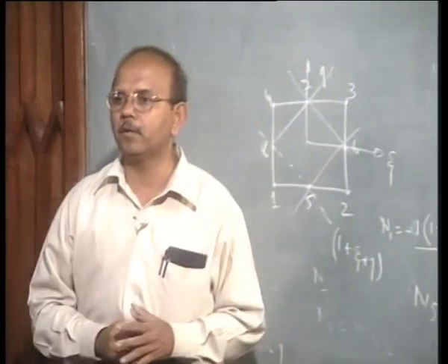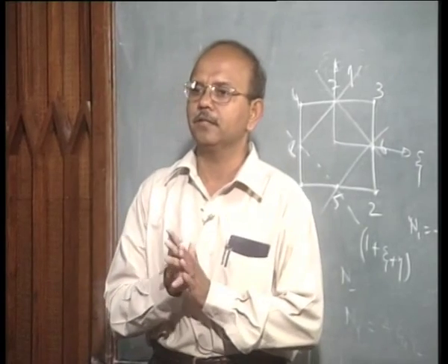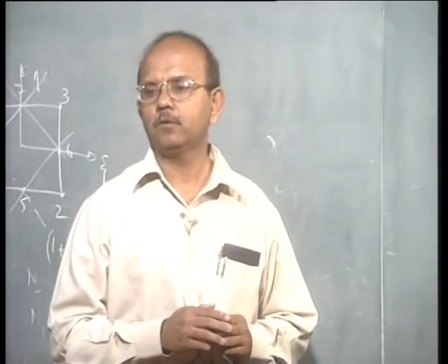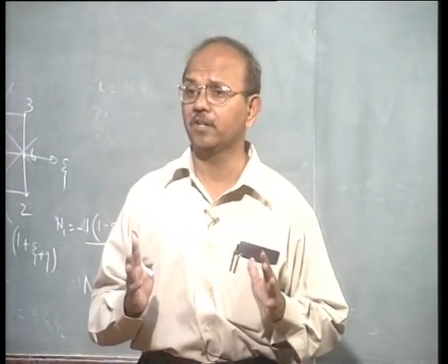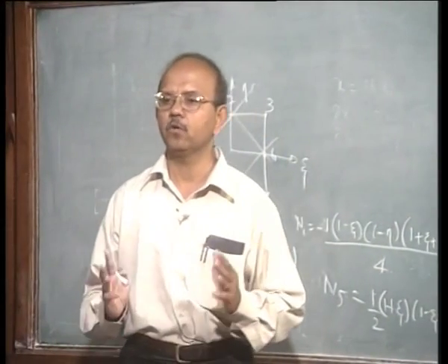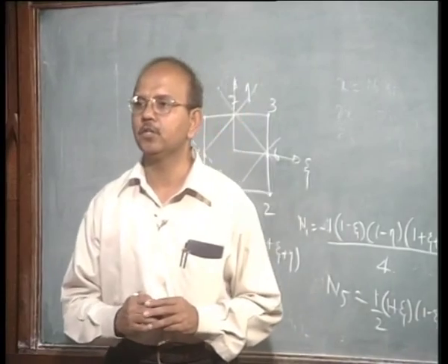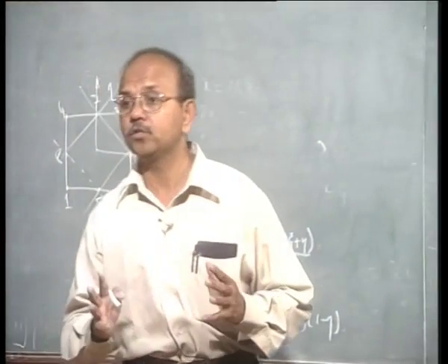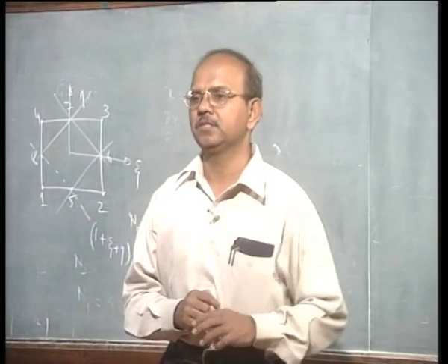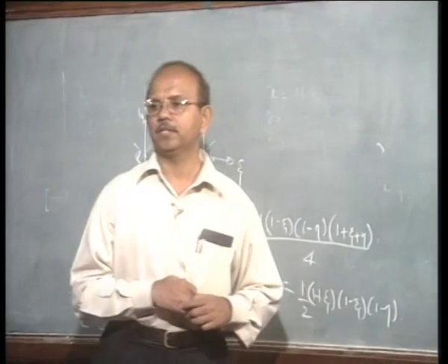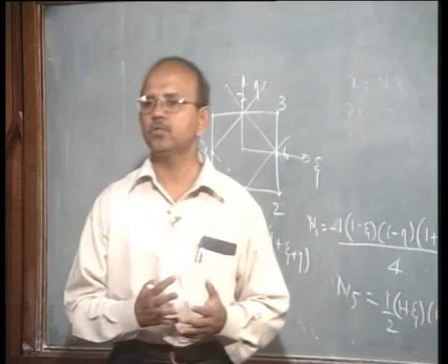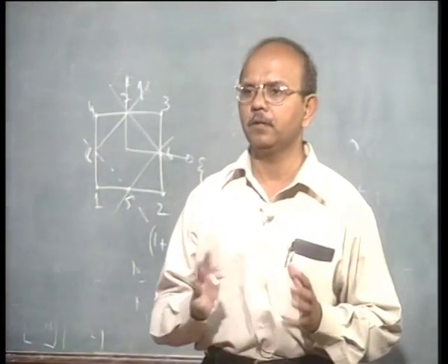Right. I hope all of you remember numerical integration, what we did before. And one of the important rules, of course, numerical integration existed independent of finite element. We call this Gauss quadrature. We also said that there are a number of ways in which numerical integration can be done. Newton-Cotes is another such formula, and in fact Newton-Cotes is used in certain shell elements because of certain advantages, but extensively Gauss quadrature rules are used in finite element analysis.